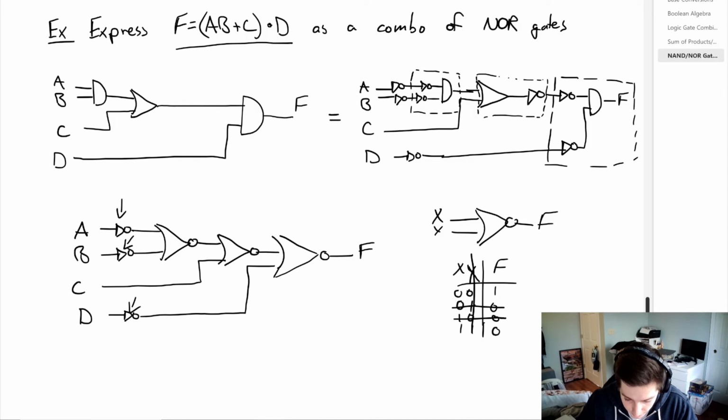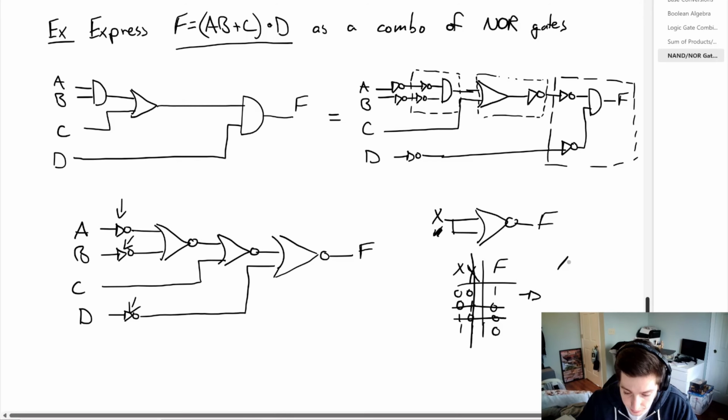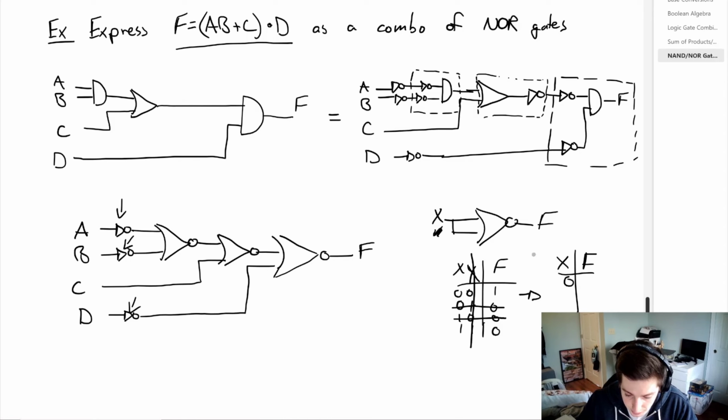Now for redundancy, we can get rid of that second X and tie the inputs together. And we can compress this truth table simply as 1 input, 1 output, 0 and 1. And what we're left with is a 1 and a 0. So what this says is that this NOR gate is equivalent to this inverter. So you could adjust these inverters to NOR gates.